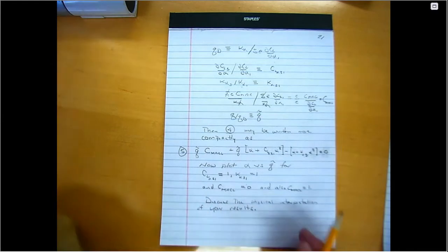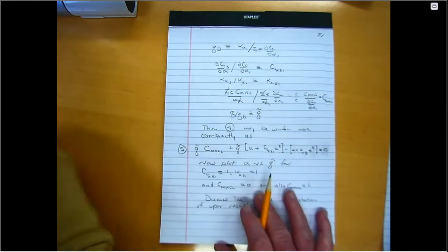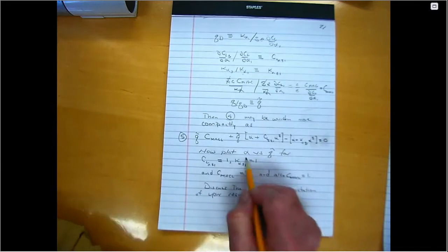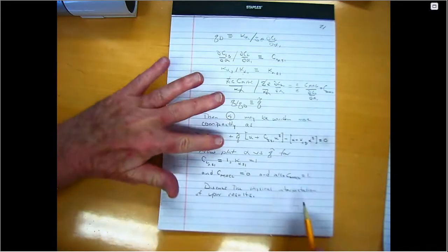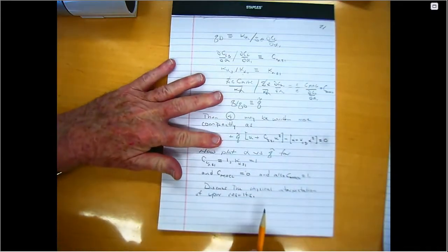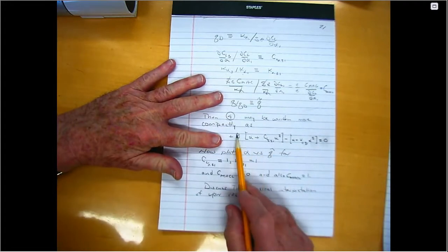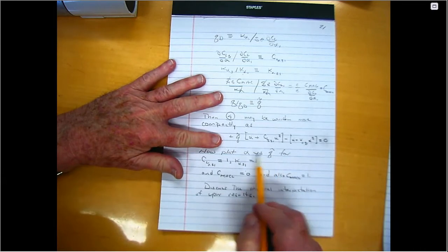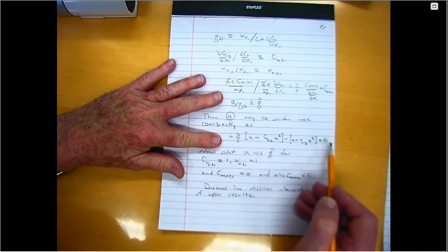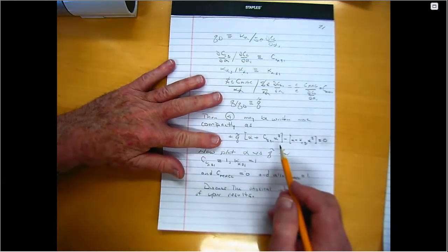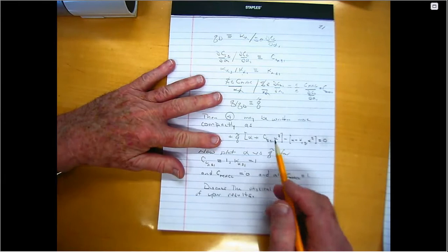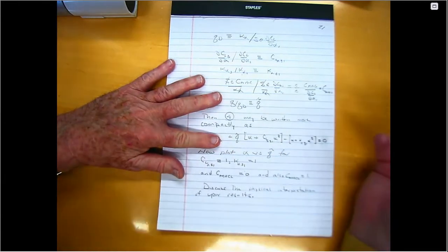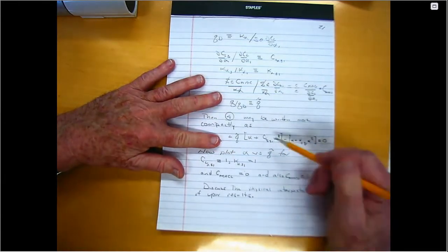Okay, now what I would like you to do for your homework is make a plot of alpha versus Q. If I delete that term, what will happen is below Q delta, which is a non-dimensional Q, right? Below 1, alpha equals 0 is the only possible solution to this equation. It's the only possible solution when I'm below the divergence dynamic pressure. But when I'm above the divergence dynamic pressure, there are actually 3 solutions because it's a cubic, right?